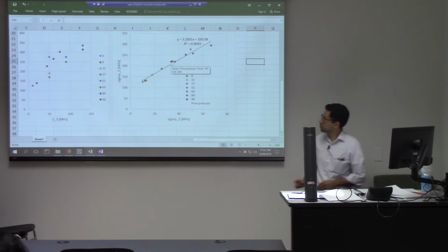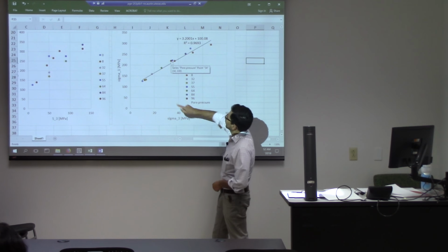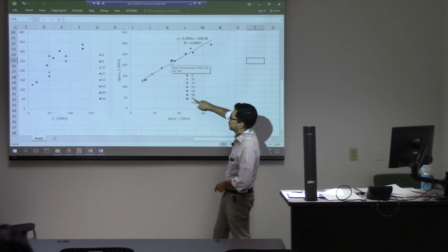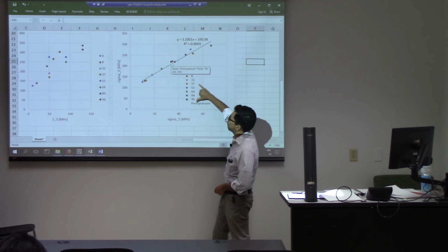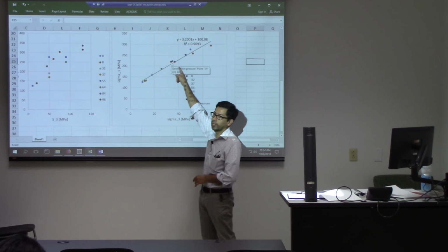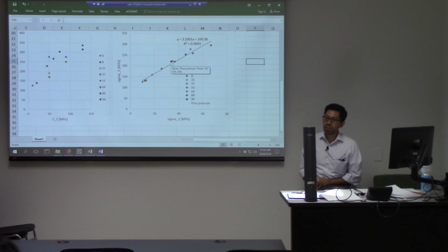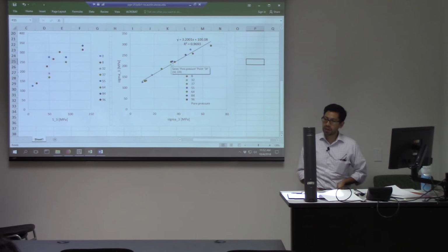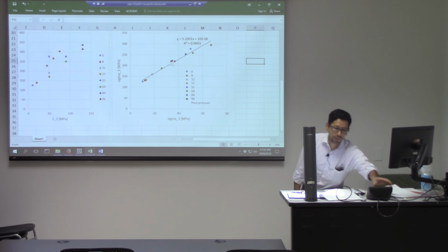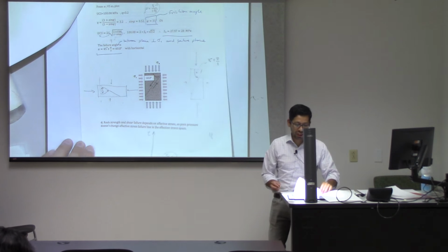And if you look, for example, at those 3 points over there, they are almost exactly in the same location, but they were done with 8 megapascals, with 55 megapascals, and with 96 megapascals of pore pressure. Quite different pore pressure. But when you calculate effective stresses, if they are about the same, they fail at about the same point. So pore pressure doesn't really have an effect on the shear strength. It has an effect on many other things, but not that much on the shear strength. So the answer to that point is that no, there is no effect of pore pressure on shear strength.